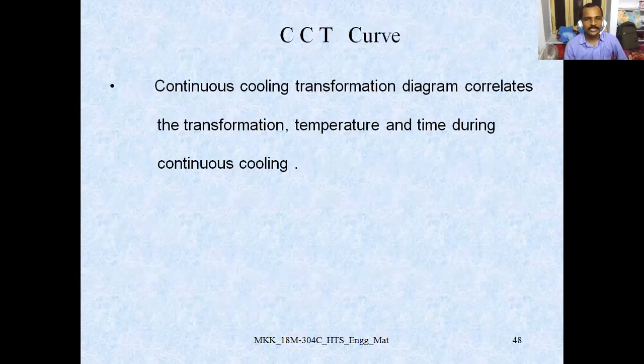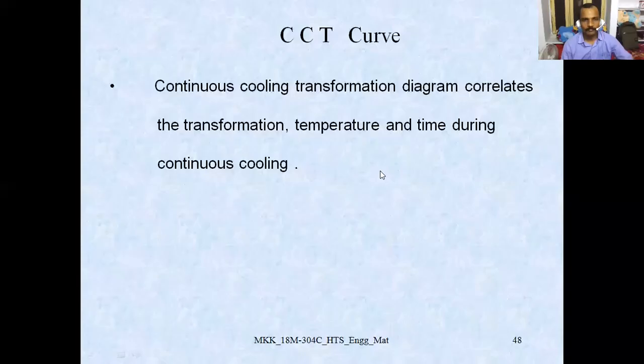Now let us move to the CCT curve, that is the continuous cooling transformation curve. The CCT curve correlates the transformation, temperature and time during the continuous cooling process.